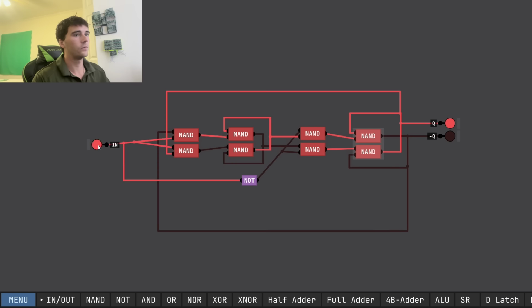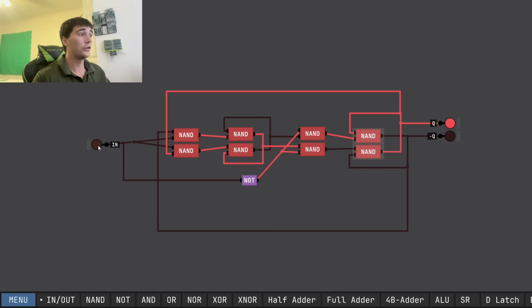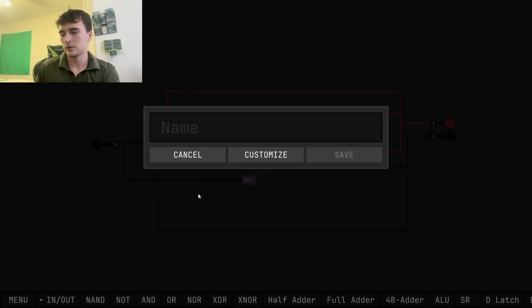And this gives us this toggle cycle, just like this, which is very useful in adding numbers by one instead of using a full ALU and register combo, which can be a little too much sometimes. So I'm going to call this a T flip-flop.